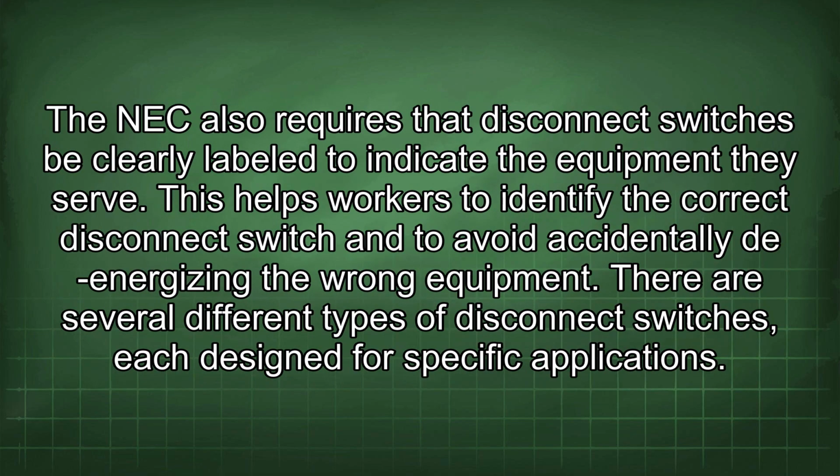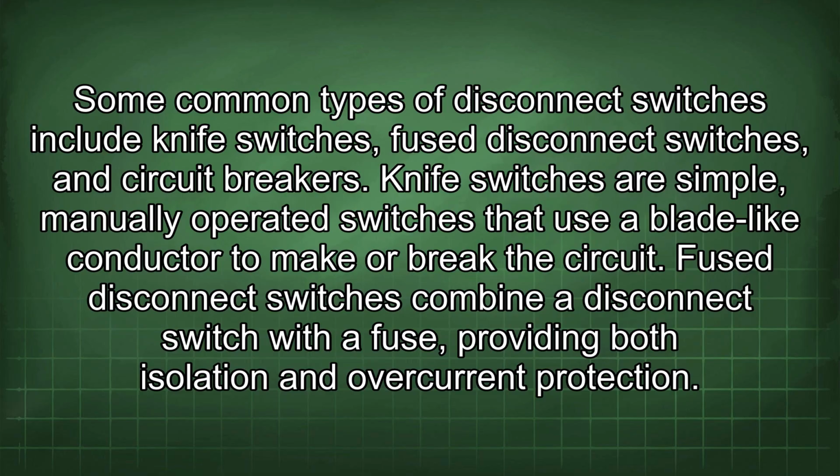The NEC also requires that disconnect switches be clearly labeled to indicate the equipment they serve. This helps workers to identify the correct disconnect switch and to avoid accidentally de-energizing the wrong equipment. There are several different types of disconnect switches, each designed for specific applications. Some common types of disconnect switches include knife switches, fuse disconnect switches, and circuit breakers.